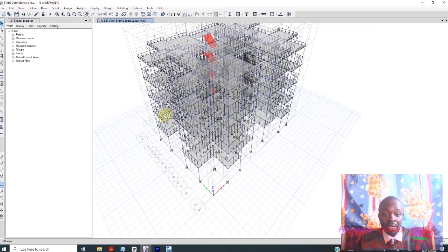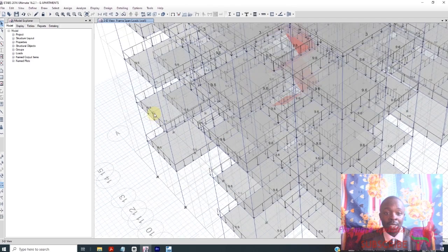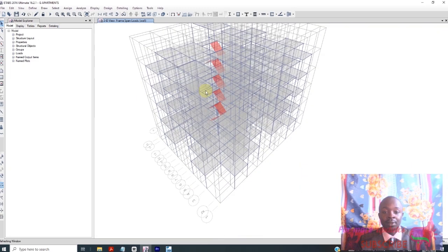So this is the load I've used for our masonry wall. Because we use machine cut rocks, this is not a load bearing wall, so we cannot assume that it's going to the steel frame. But from the foundation to the foundation level, we used load bearing walls from Bahati Barrow, that is rock blocks. But for the rest of the floors, from story one, from the plinth level to the top part, we used machine cut rocks. So I've done the same here.